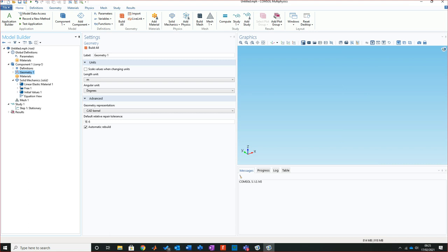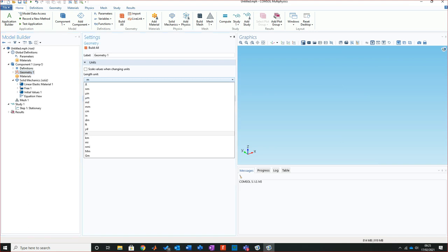And when I brought it in, the values were coming back 1,000 times bigger. I'm thinking, what have I done wrong? I don't understand. This was a week of me messing around. And I realised this was set to meters. So even with imports, if you set this wrong, this can come in massive. So do keep this in mind.